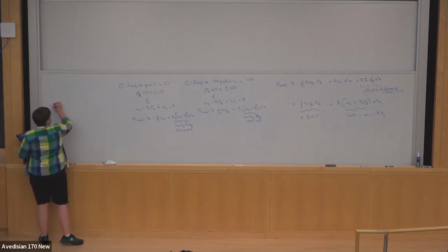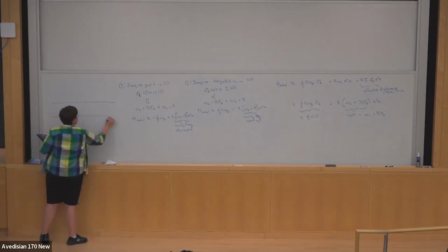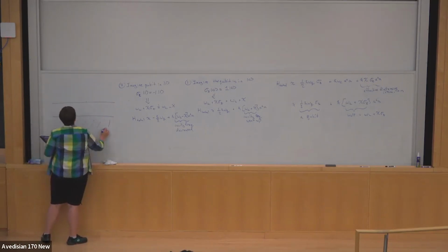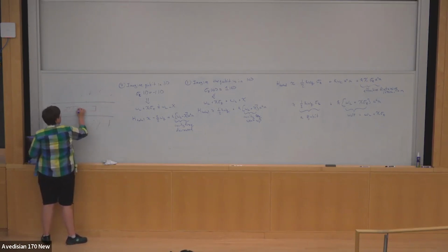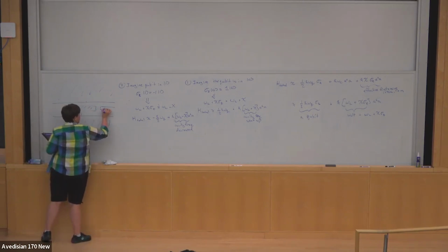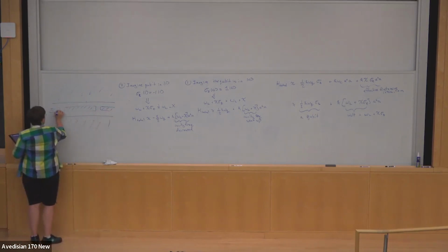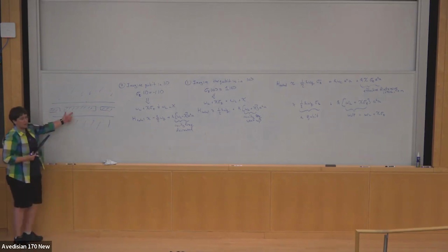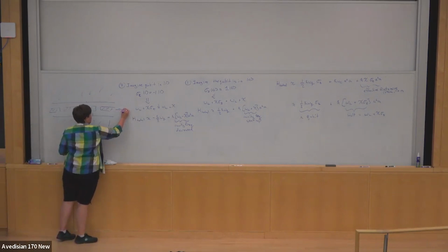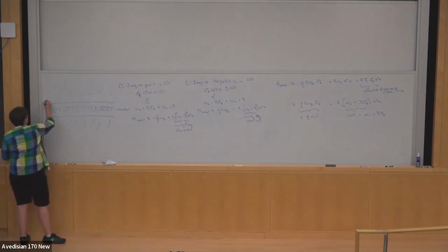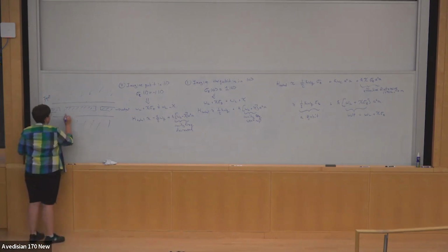And so now let's go back to thinking about our coplanar waveguide resonator. We have ground plane, center pin, and now I'm going to really explicitly add these two ports. This part is a resonator, and this is a piece of coax. This is going to go to the output, and the input comes in here. And we put the qubit in.